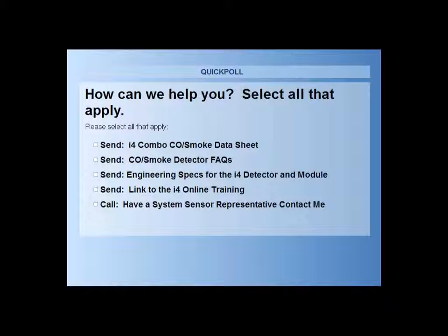Doug, a specific question on 520 hertz. We know that there are some new requirements for that low-frequency sounder for those jurisdictions in NFPA 2010 and 2013. They're asking here, will the sounder in this detector meet the new 520 hertz requirements effective January 1st for sleeping spaces? No, actually, a separate 520 hertz sounder would be needed. We do make those separate sounders, and the sounder strobes as well. Those can be found on our website. Okay, very good.